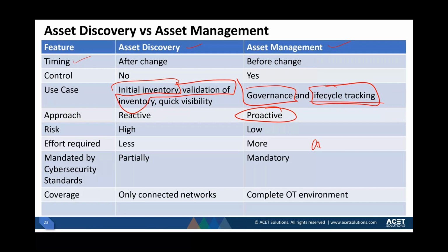I will not name any tools, like I stated before, but it is possible to do asset discovery on DCS environments. It is possible to do asset discovery on industrial facilities. I have personally done it. But whether you use asset discovery or not, the message is don't forget the asset management part. Focus on asset management first, and then think of what discovery tools are compatible. You may use multiple tools, some from the DCS vendors, some from third parties. But if you have a central asset management solution, you can pull information from different tools and still have comprehensive asset management.